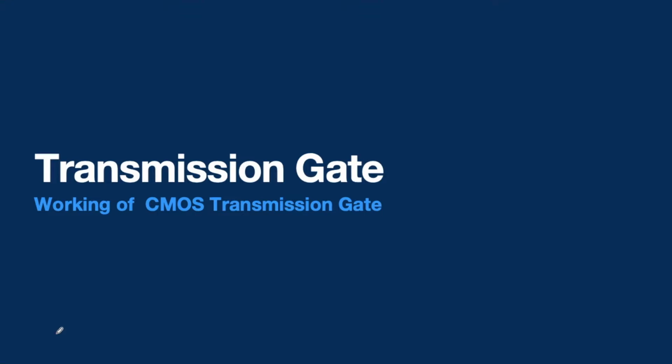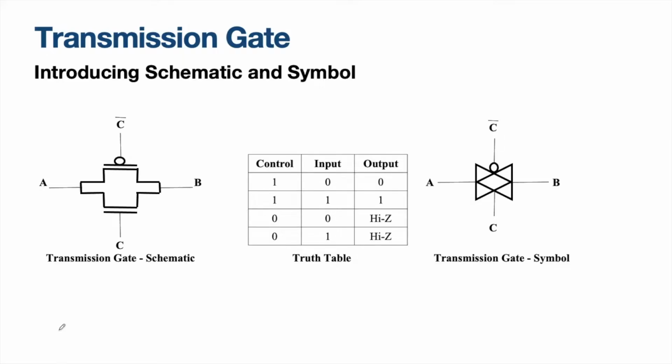In this video, we will be learning about a simple transmission gate and how it works. Here is a schematic of a transmission gate where we have a PMOS transistor on top and an NMOS transistor at the bottom. For a PMOS transistor, we have to give the control signal in its inverted form. For an NMOS transistor, we have to give the control signal directly.